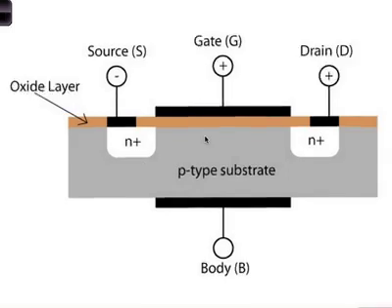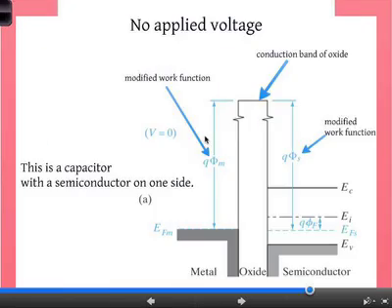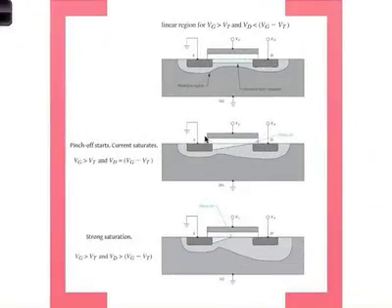So let's talk about the capacitance quickly. We did the qualitative analysis, so I'll skip that. The other important thing, of course, is that we have a pinch-off situation here as well. As you increase the gate voltage, at some point the depletion region starts encroaching into the inversion region. This light blue region is the inversion channel, inversion because it has become N-type from P-type, so it has inverted its type.